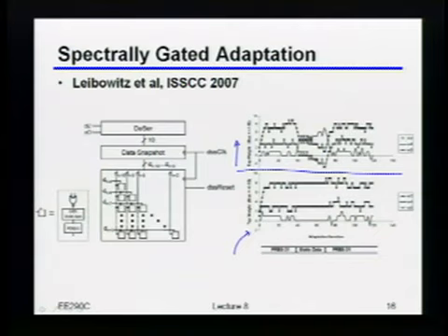Okay, and so the way to read these time axes is, for some period of time, they're sending 2 to the 31 PRBS data. Then, for some other time, they're sending some static pattern, as an example, an idle sequence. And then again, they're sending some 2 to the 31 PRBS data. Okay? So what you can see is that if you don't take care of throwing away bad updates, all of a sudden, while you've got that static update, you're converging to something completely different. Right? Each one of those traces is just going off and doing something weird. Right? And then eventually, when you get the real data again, maybe it converges to the right spot.